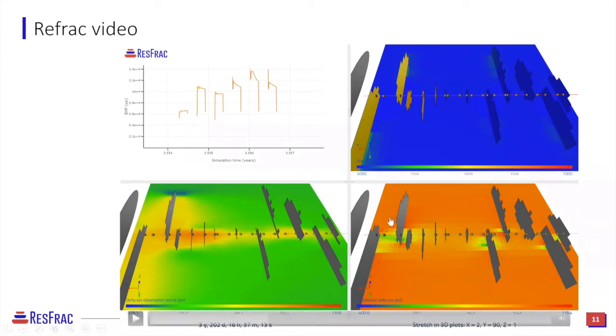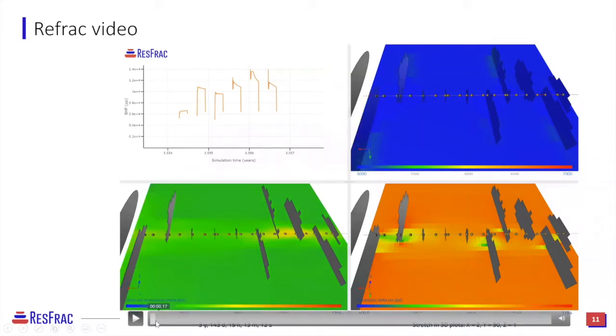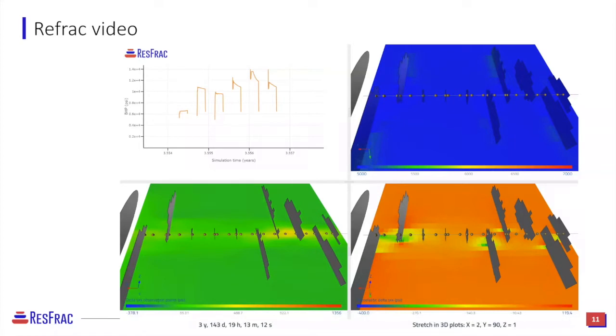Yeah, so there are 2 components to that, I think, right? Over here on the left-hand side, this is showing the delta stress due to that aperture change. Some degree of that is going to be locked in. Of course, when you're pumping and the fractures are wide open, it's at a maximum. But even once the fractures close down, there is proppant within that fracture.